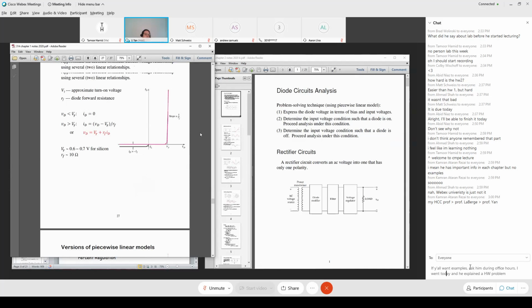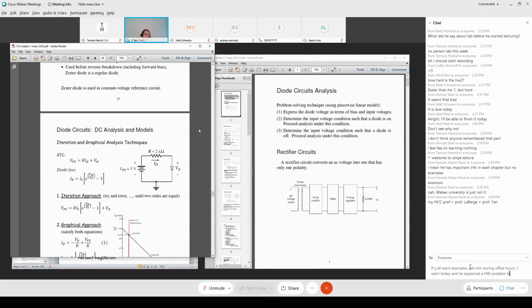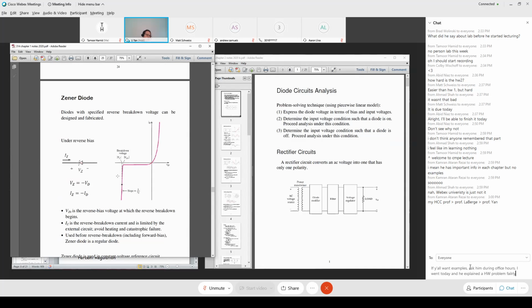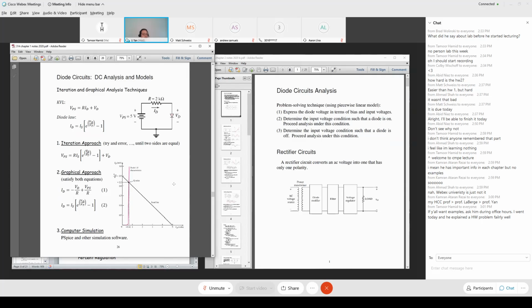But the Zener ideal diode is referring to the fact that we're not operating in forward bias, and not in regular reverse bias. We are operating in reverse breakdown. You have to describe this current-voltage relationship for the Zener diode. How do you describe this straight line mathematically? This straight line is exactly described by this formula.